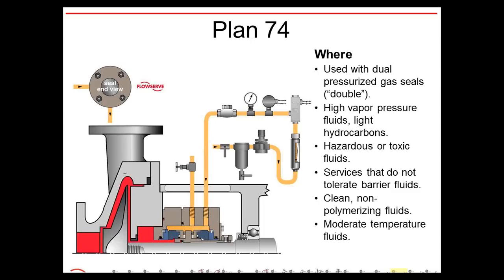With gas seals, you definitely want to make sure you have a very clean system. They've come a long way with how clean the systems have to be. It used to be that any dirt or contaminants would hang up and fail a gas seal very quickly. They've come a long way with design, and now you're starting to see gas seals in pump systems where you normally wouldn't have seen them say 5 years ago. So you're going to see more and more of these in the future. And again, the Plan 74 is pretty much the default for pump gas seal applications.